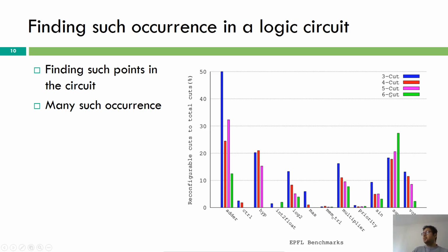In the case of square, if you consider a 6-input cut, you get around 40% self-dual functionality, and this all depends upon the benchmark and the profile you want. So if we have such self-dual logic gates in the generic library, you are bound to achieve better mapping as compared to the traditional CMOS-based generic library, which does not have specific self-dual functionalities.